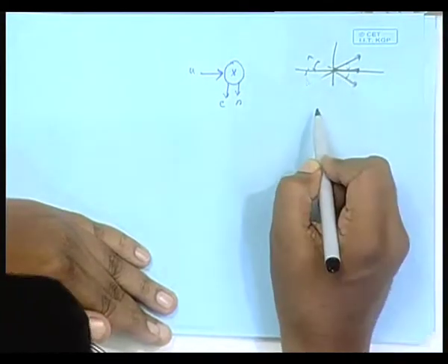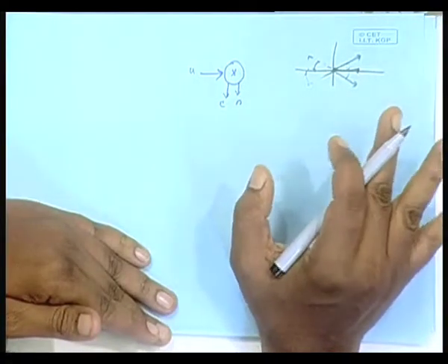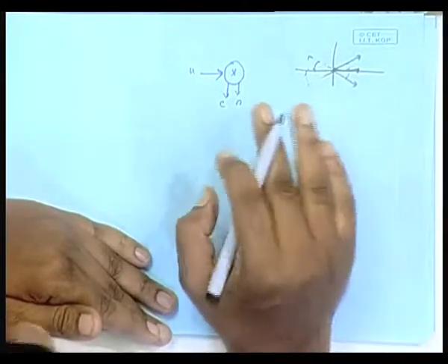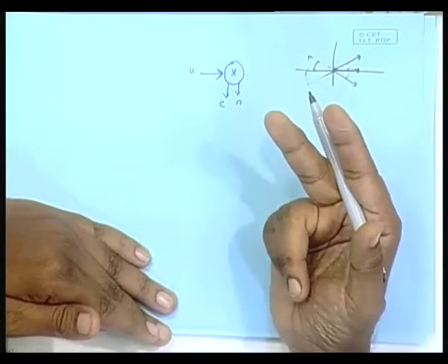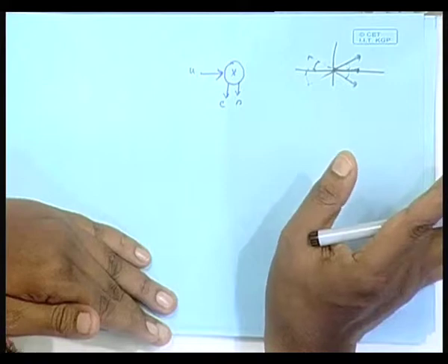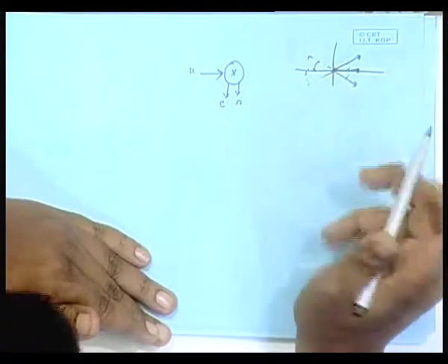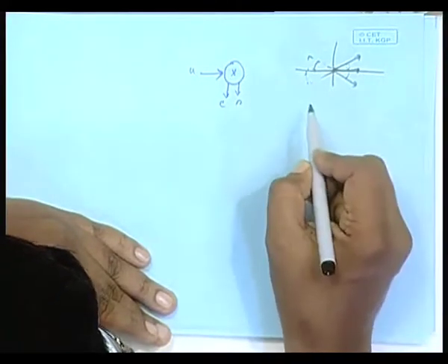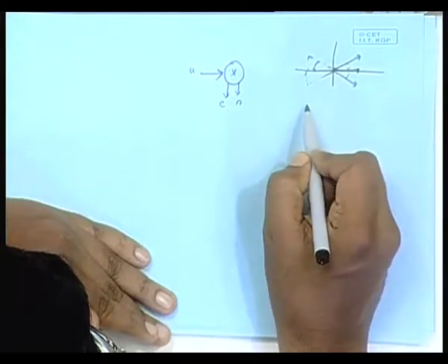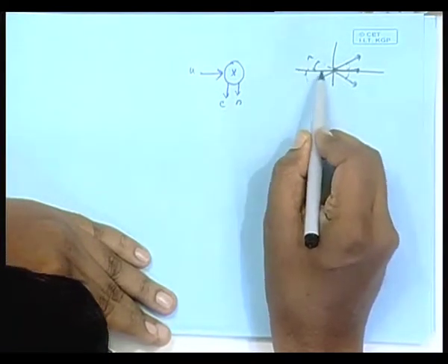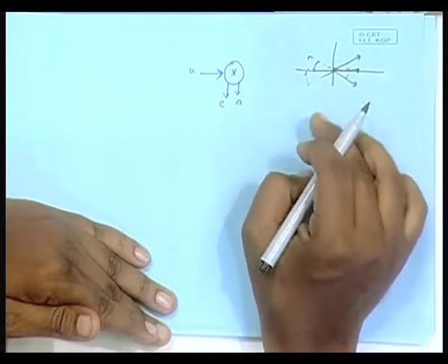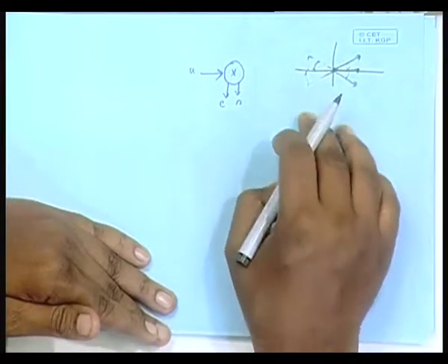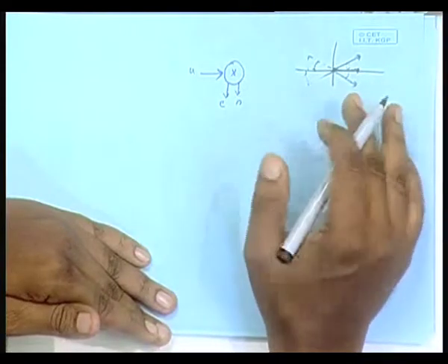So, yesterday you wrote those mod x by, those things are not required in hardware, these are more complicated. The sign of a number is very easily found out in hardware. You have to take the sign bit only. So, this book is old style, it's better not to use those kind of things. And the special case when this u is 0, that time even no computation is required, so that case we take out separately, otherwise the remaining part also takes care of that. But why do the computation when this is trivially operated?